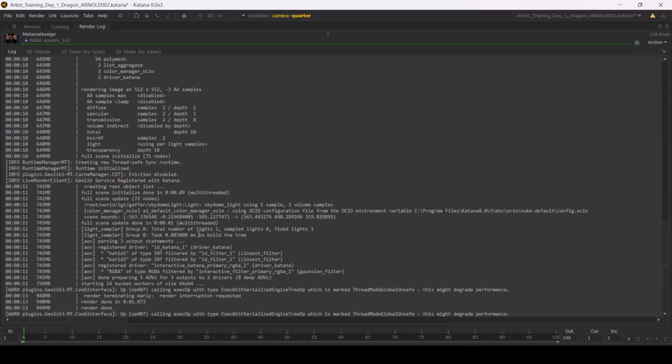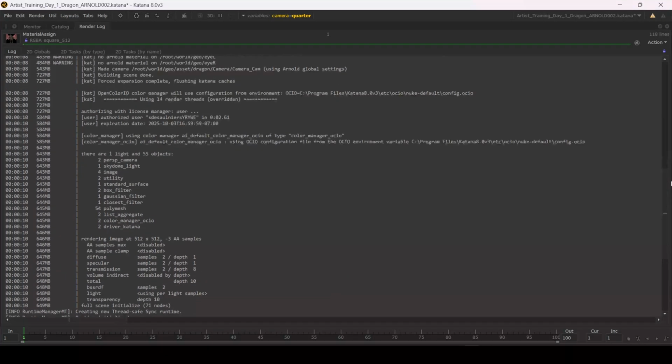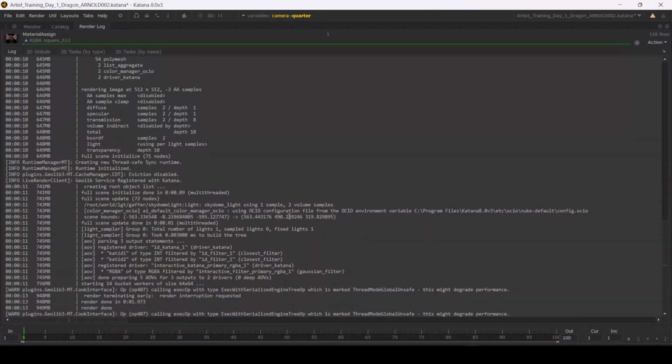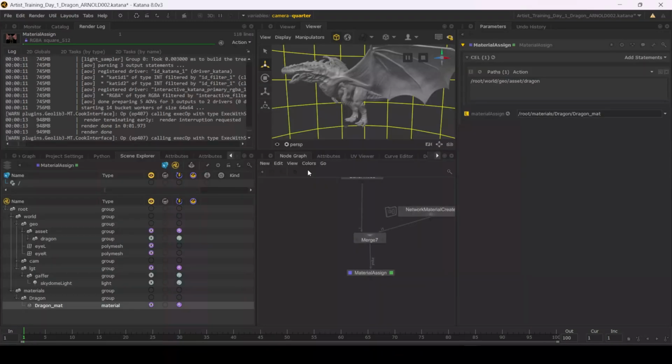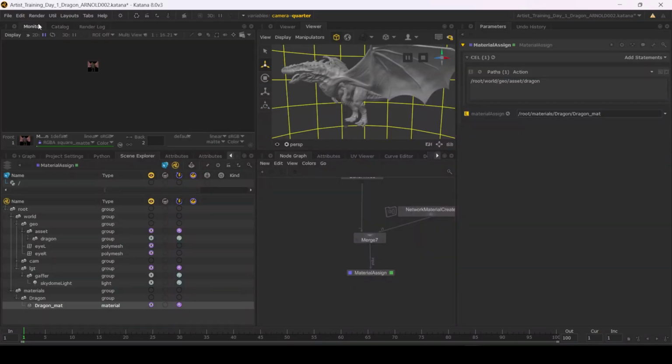One of the errors you'll see at the bottom of the log quite often is Arnold license violation. Do not read the last report. Just scroll up and go read what else is written in your log. You'll get better information of what needs to be changed and what is causing it to error out.